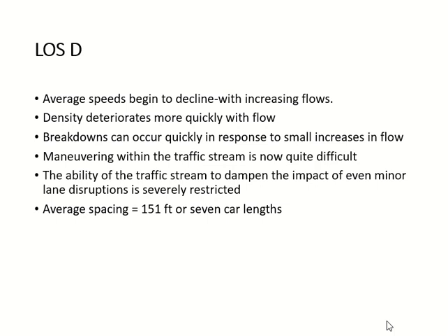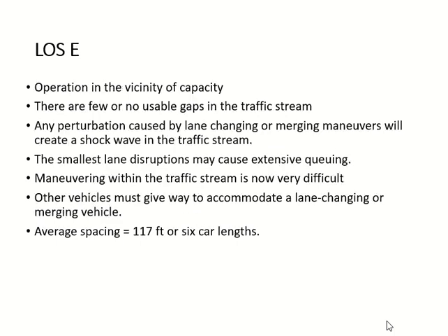Obviously, maneuverability is very difficult now. The spacing has become even lower than the last case. And now even a minor disruption has a big potential of causing a major breakdown in traffic. Okay, like more potential than the level of service C. So spacing is now even getting lower.